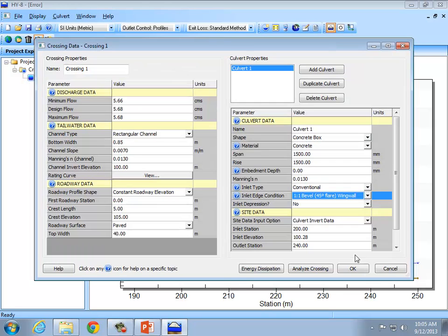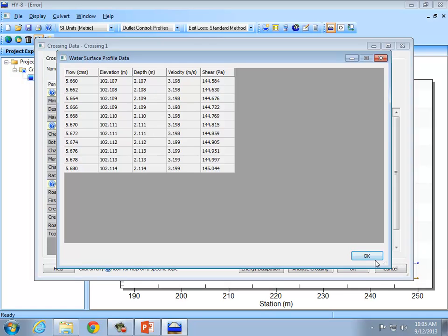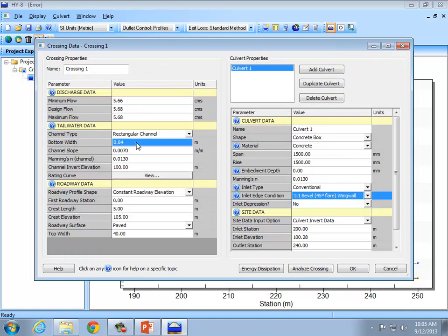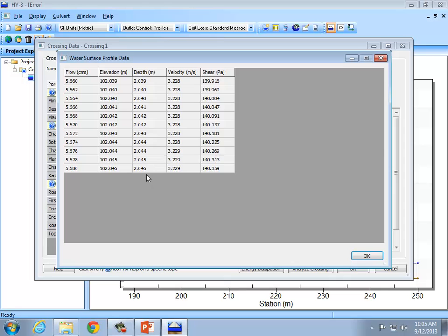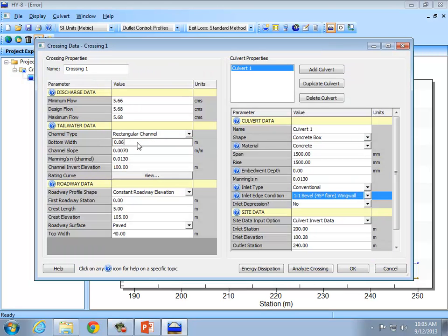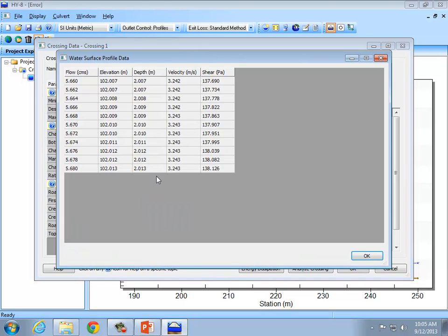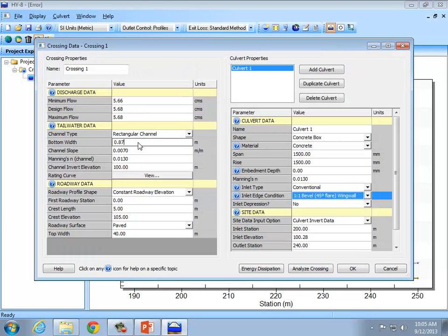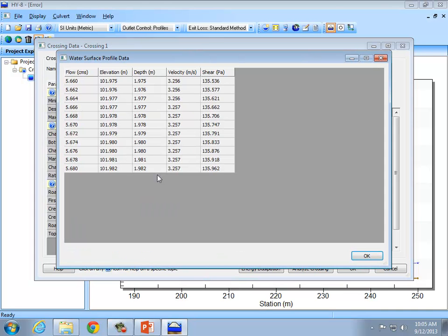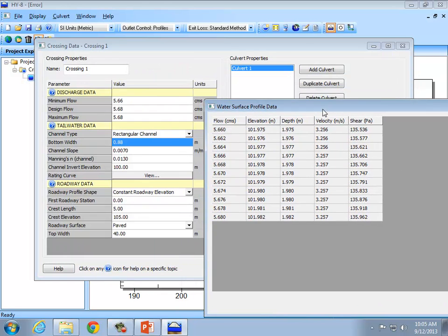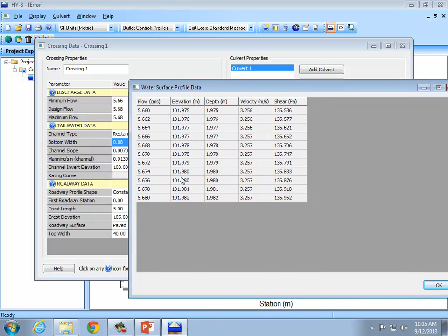We're just over. So maybe 0.84. And we're finding what channel width. That was the wrong direction. 0.86. Getting real close. 0.87. How wide must the channel be? And there we are. The channel width of 0.88 now is making the elevation of the water downstream equal to 2 meters.